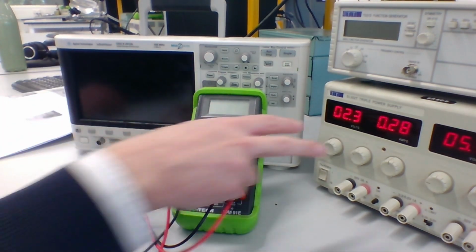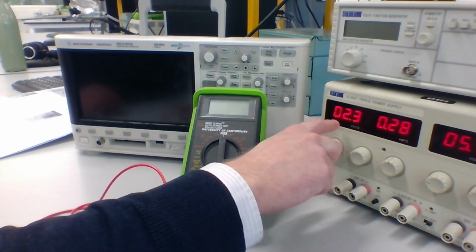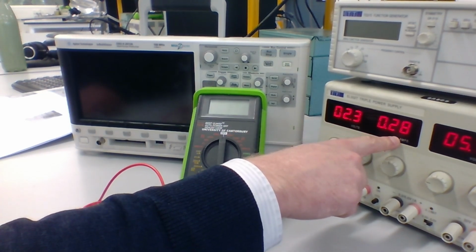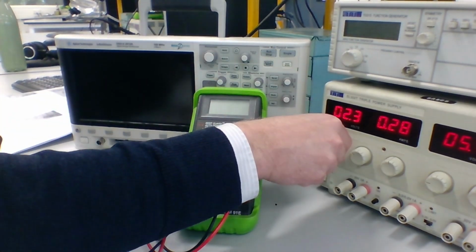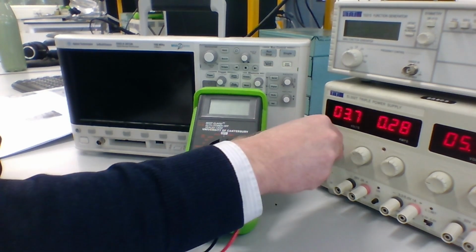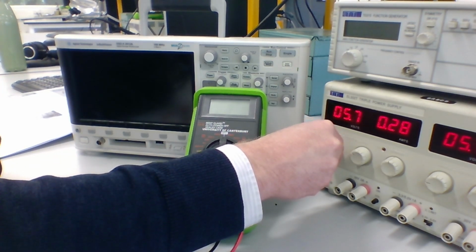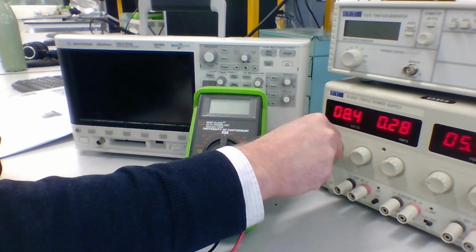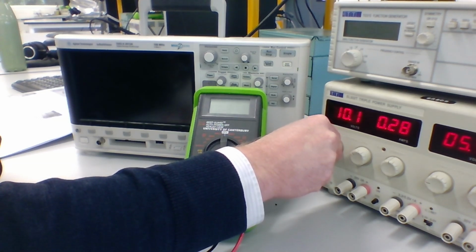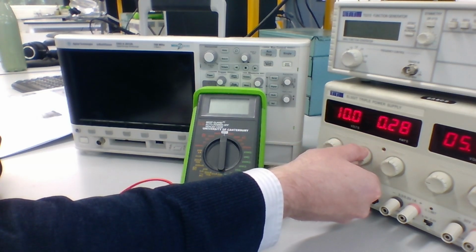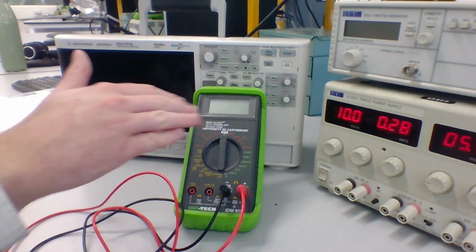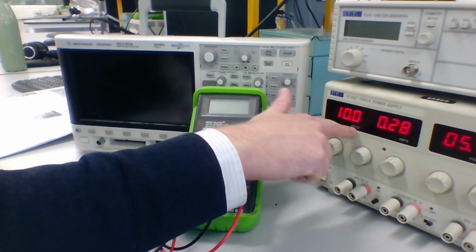Okay, we then have two settings on this power supply, the voltage and the current limit. Firstly, I'm going to set the voltage. We want that to be set to 10 volts. So I'm going to turn the dial here. There are two dials on this power supply, coarse and fine. Coarse is for doing rapid adjustments, set to 10, and we can use the fine dial for small adjustments, like that. Now it is set to 10 volts, which is what the readout here is showing.